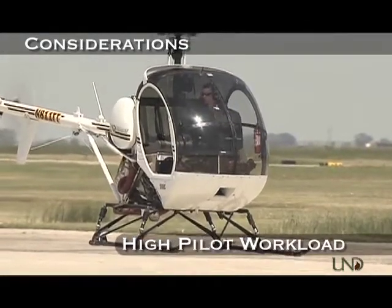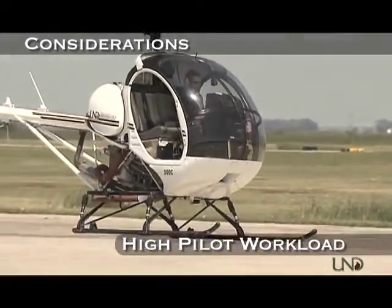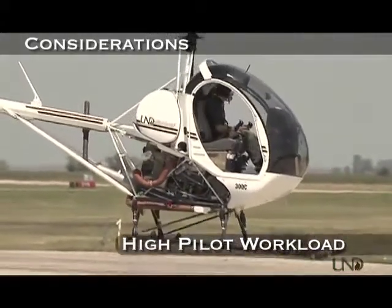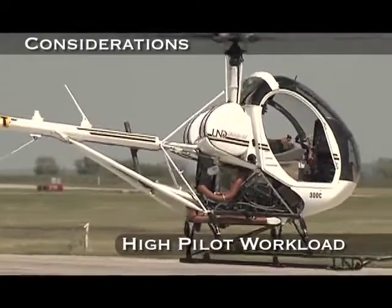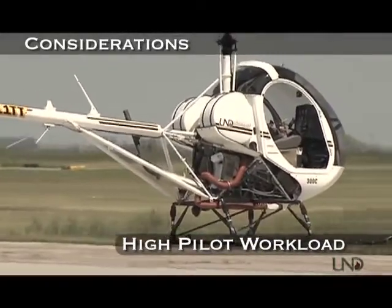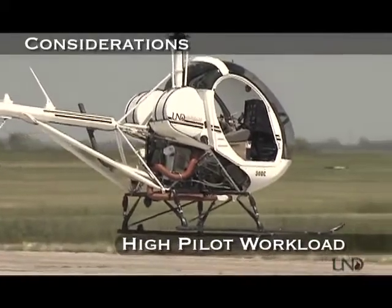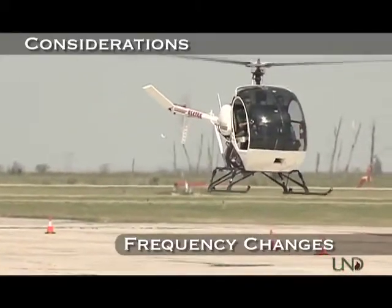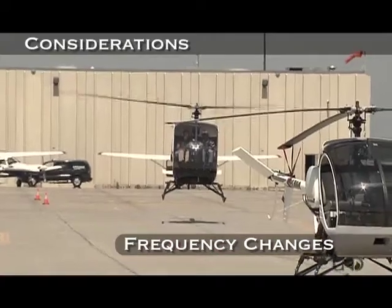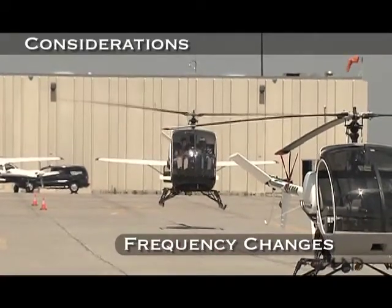Hovering or hover taxiing in close proximity to the ground can be demanding for pilots since it requires a lot of concentration and manipulation of 3 different sets of aircraft controls, as opposed to 2 for fixed-wing aircraft. Air taxiing is easier and reduces pilot workload. Since operating close to the ground is so demanding, especially when the helicopter is being operated by a single pilot, frequency changes should be minimized or not given at all.